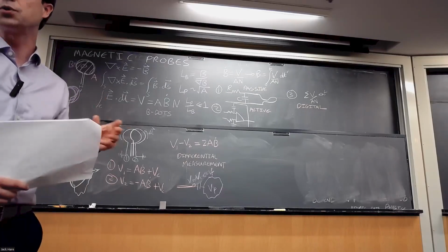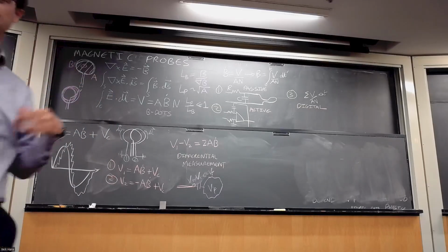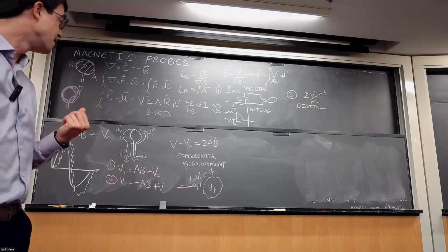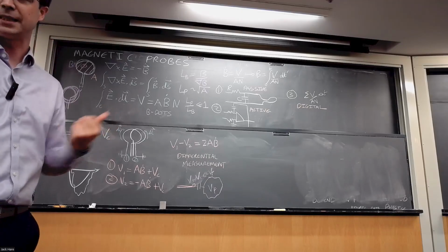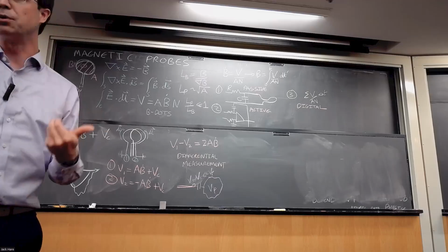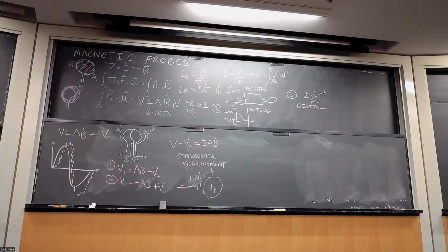It's a good question, but say you've got a voltage that you're measuring, and you're measuring it over a 50 ohm terminator, which is what we normally do for the matching with 50 ohm cables. That's going to be a pretty small current. So the magnetic field you're inducing is pretty small. It's a good question. Okay, all right, thanks.